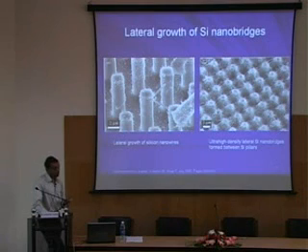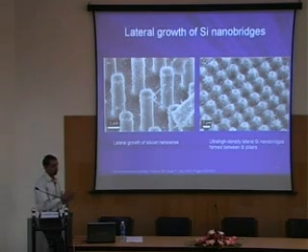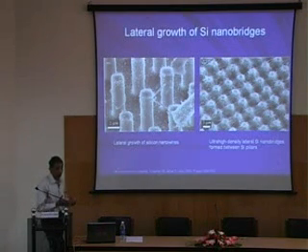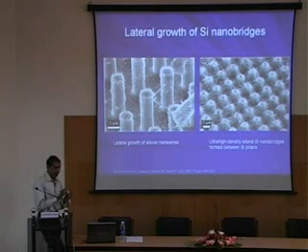But you have to make sure that when you deposit these quantum-size gold droplets, they do not combine with each other and become a bigger droplet. In order to do that, you put this entire thing in a long-chain polymer environment, so that these long-chain polymers will keep the gold droplets apart. That is very important here.